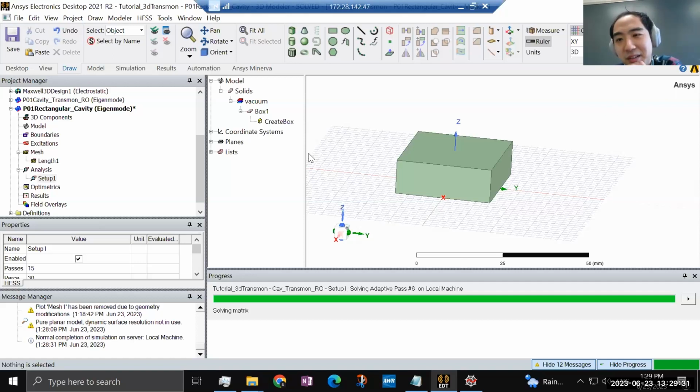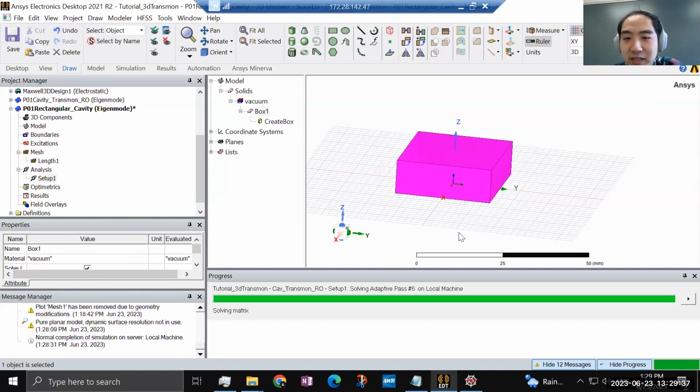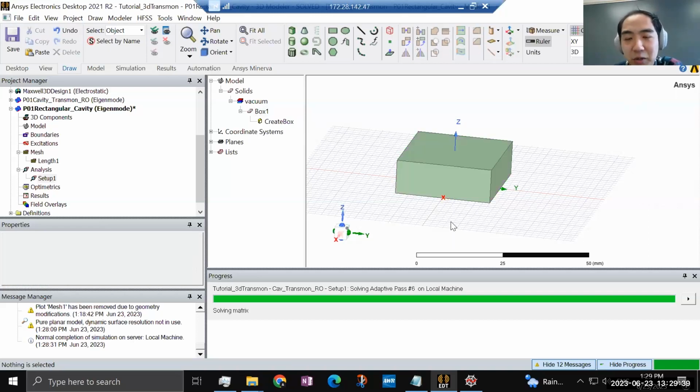There might be a smart way to convert that into the intrinsic objects built from HFSS, but the easy way to parameterize the design is to make all the design in here. Eventually you have a CAD software that you are most familiar with, and when you do enough simulation with HFSS, this becomes your most comfortable CAD drawing software.